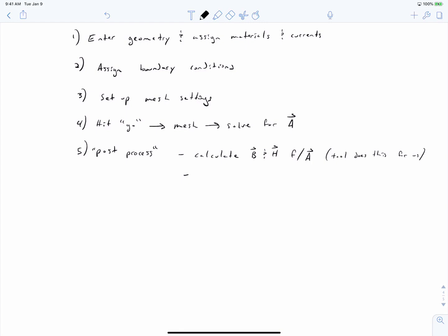And then, because we're evaluating an electric machine, we presumably have some performance metrics in mind that we need to calculate in order to determine if this is a good design or not. And we calculate that from our magnetic fields. And these performance metrics will be things like forces, torque on the shaft. It might be losses in the machine. It could be inductances, power factor, reactances, you name it. You have to define that, and you have to implement how you're going to calculate that, because the FEA tool does not know what you care about.